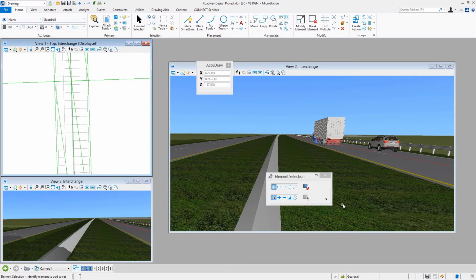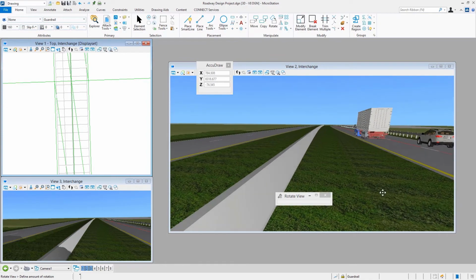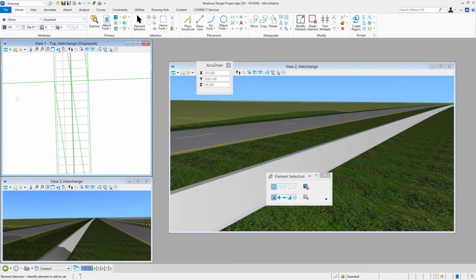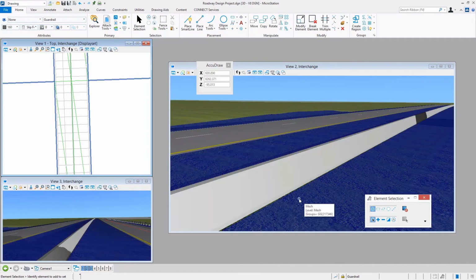Again, this can be created and placed very easily through a variety of different placement commands through the applications that you're working with. It can essentially be about that simple to create something like this using some very basic 3D geometry in MicroStation. The geometry can, of course, be much more complex than what I showed you here, but it doesn't always have to be, so you do what you need to. By using those short little sections repeated over and over, this gives us a nice smooth appearance even when we place it on a curve, unless the curve has a really small radius. So it works out pretty nicely, as you can see.